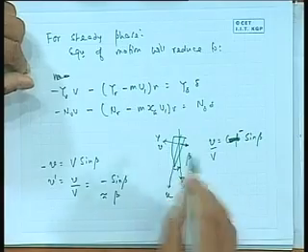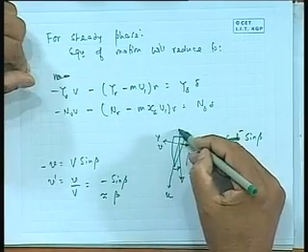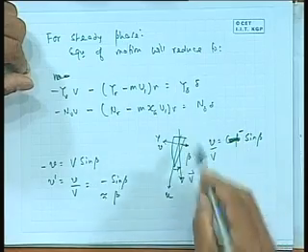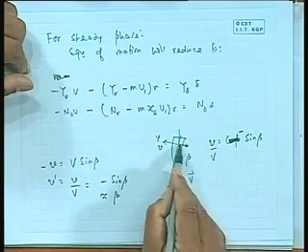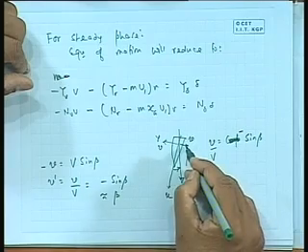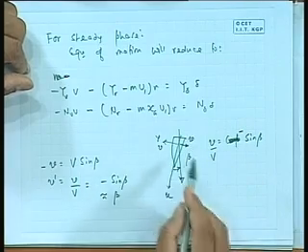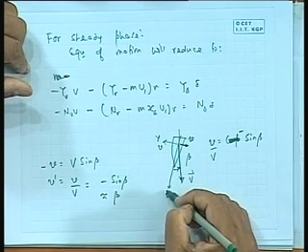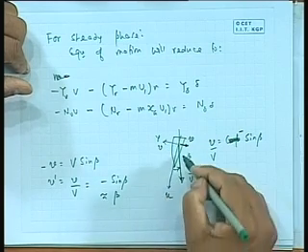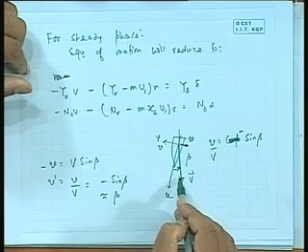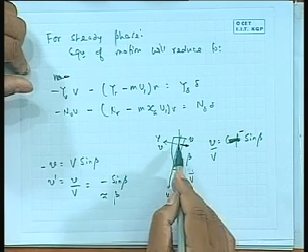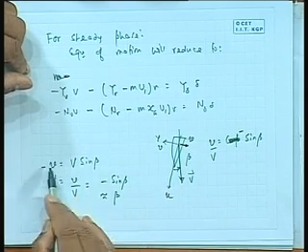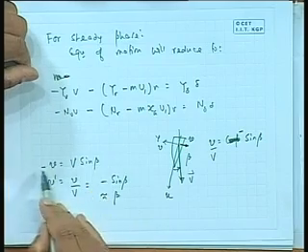So the drift angle is nothing but the non-dimensional sway velocity. This diagram may not have been clear, but if this is my V axis, this is my u here, and my small v is this one, because you can draw a rectangle. These are the two resolutions. This small v is nothing but V into sin beta, but v is negative for positive beta, therefore v dash is minus beta.